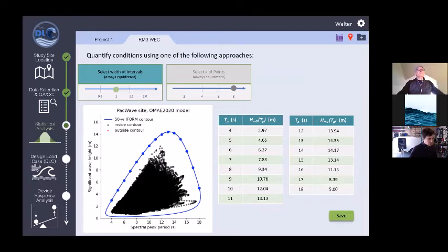Ryan and Vincent, it's very nice that you outline the boundary and the wave excitation. I wondered, did you use the tool to go through detailed design of the components? For example, no matter which concept you choose, PTO or mooring system, to say how large the system will be. The reason I ask is that with the 50 year wave, plus the safety factor, you design all the mechanical system is very, very bulky. Did you use this tool to go through some particular concept?